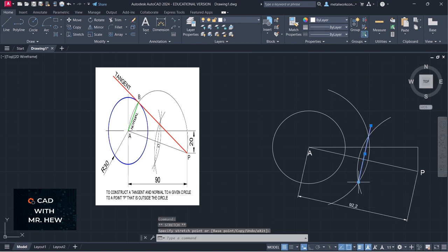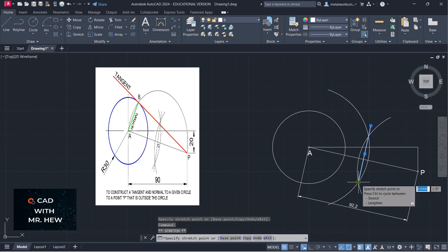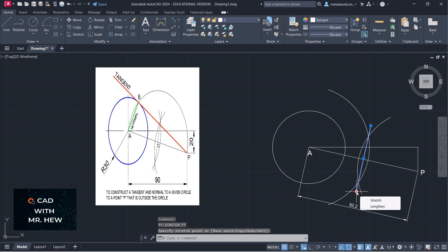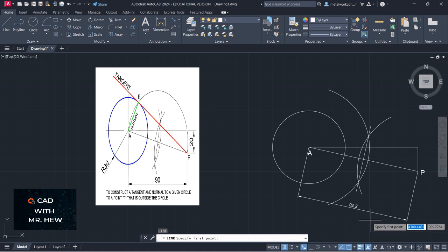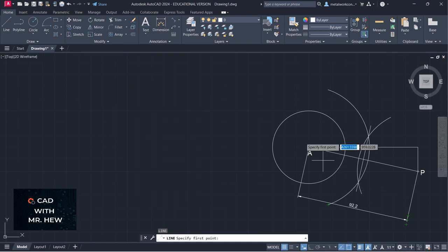So we click on here, enter. All right, the next step: these arcs are too long. If you were using your compass, you would stop it at the appropriate place. Since we went beyond where we should draw it, just to let our drawings look neat and tidy, I'm going to break it. So we're going to go to the modify command.